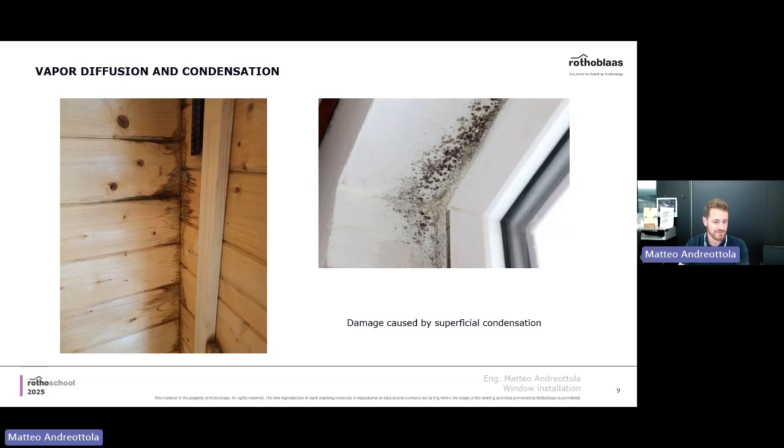And even if they've just followed the lesson, even if they know exactly what the issues might be, I pass through the groups, and I see a lot of issues in the corner anyway. This is because when you're putting a profile like a tape on the corner, it's actually easy to leave a gap in that location.